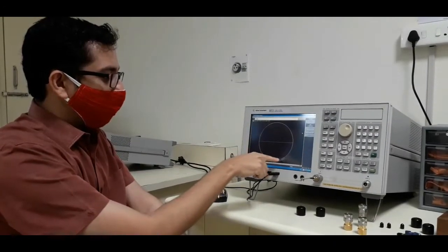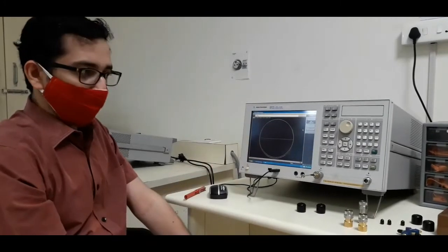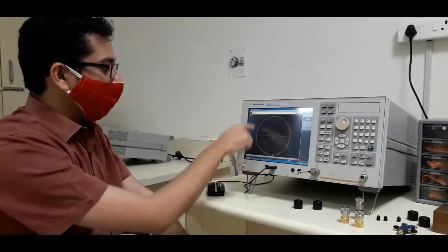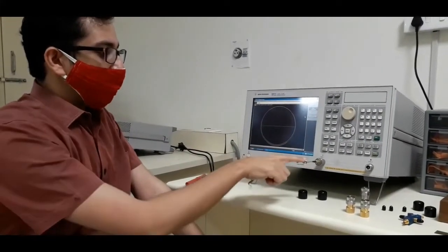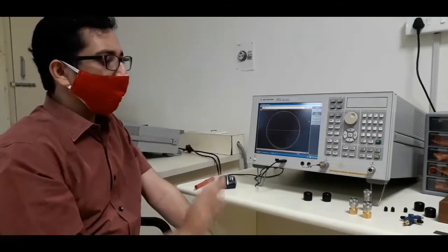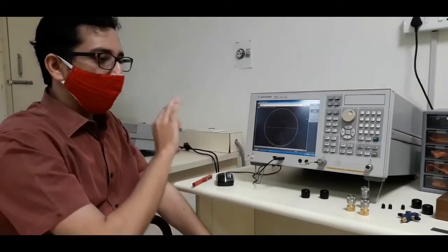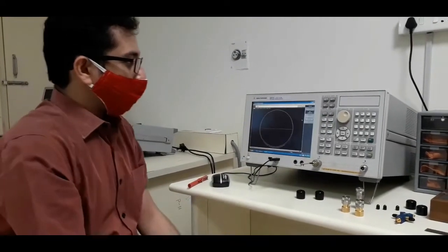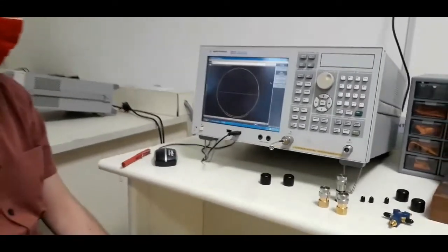So what you can see is that this green line is very close to the outer boundary of the Smith chart. But it is not exactly a circle, rather it is behaving in a spiral way. So just by looking at this, we can say that this line has some small loss characteristics. That means, as is practically more available, this is not a completely lossless line, but it is something like a low loss line. Alright, so let us now see more into this instrument.